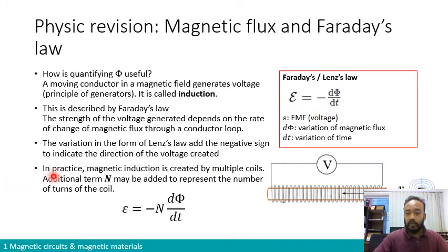And in practice, here is an example over here. I'm sorry, my video is over here where you cannot see the whole picture. Basically, we have a permanent magnet over here with a certain magnetic field, right? So if you take a cross-section area of this space inside the coil, you have a section A. If you push in and pull out the permanent magnet, what happens is that across that surface area you see a variation of flux, d phi over dt. So you will create voltage inside the coil, and you can measure a certain voltage, right?